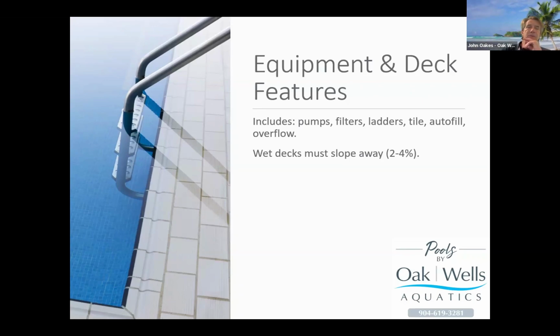The autofill over the side of the swimming pool would be an obstruction on the deck, and the health department doesn't allow that, so it has to be over in the equipment area. But on the collection tank, if you turn the pumps off, the water level in the tank equalizes with the water level in the swimming pool.